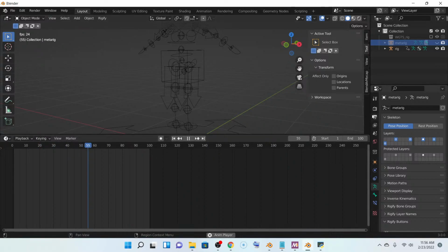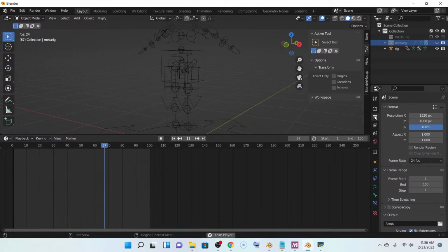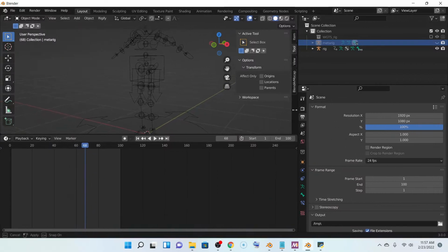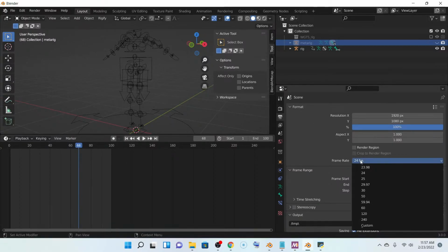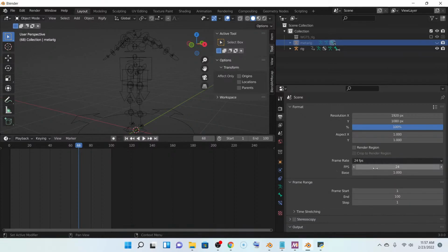You go over here to the right of the screen. You go to format. For some reason it's not coming up to have the play going. Output properties. Go to output properties, far right module over here on the screen. Go to frame rate. This is powerful stuff. Pull this out. You go to frame rate, change this. You can change it to whatever you want, but let's go to custom so we can bring up this custom option.